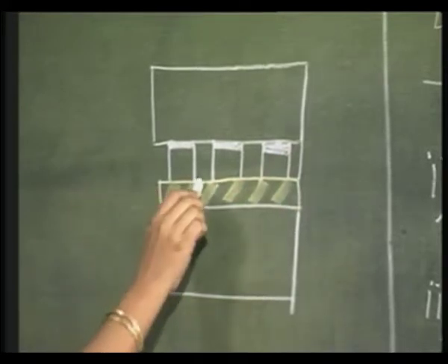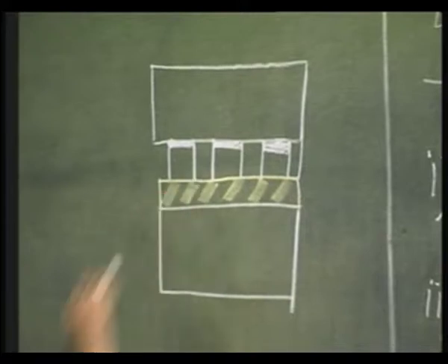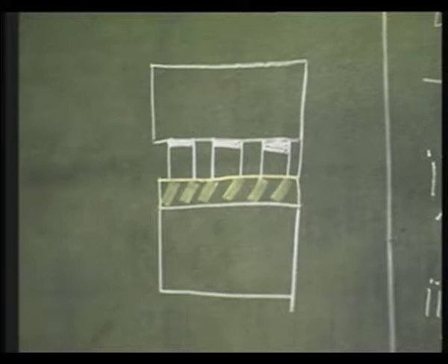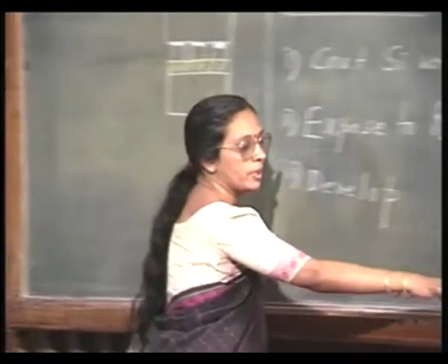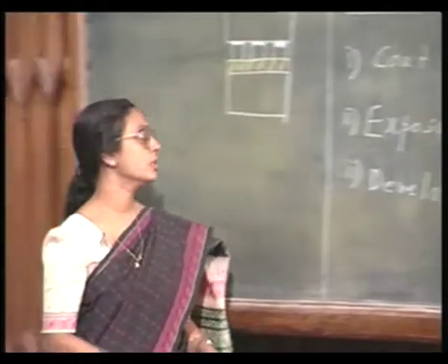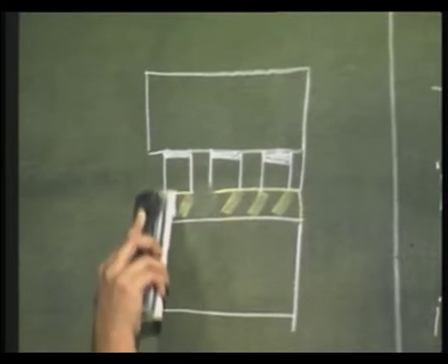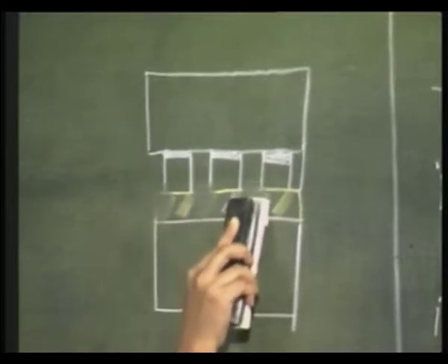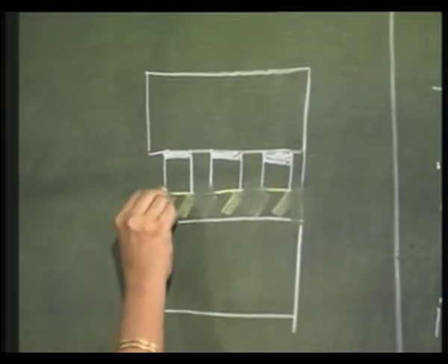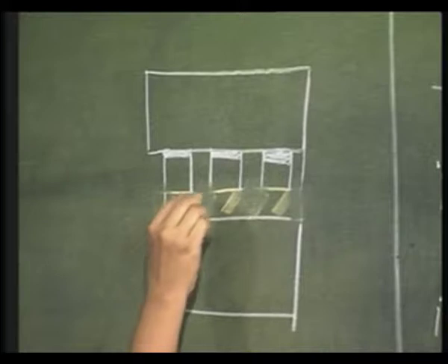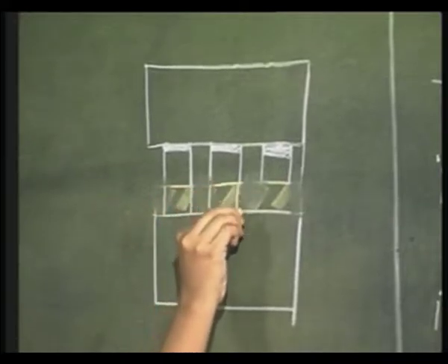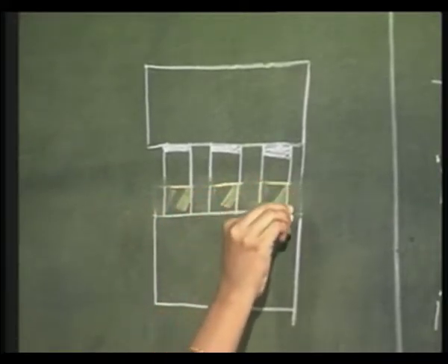The photoresist directly underneath this is exposed to radiation, and now it has become soft. It is easy to remove. So, when I put it in the developer solution, these portions go away, leaving me with resist films only in the unexposed regions.